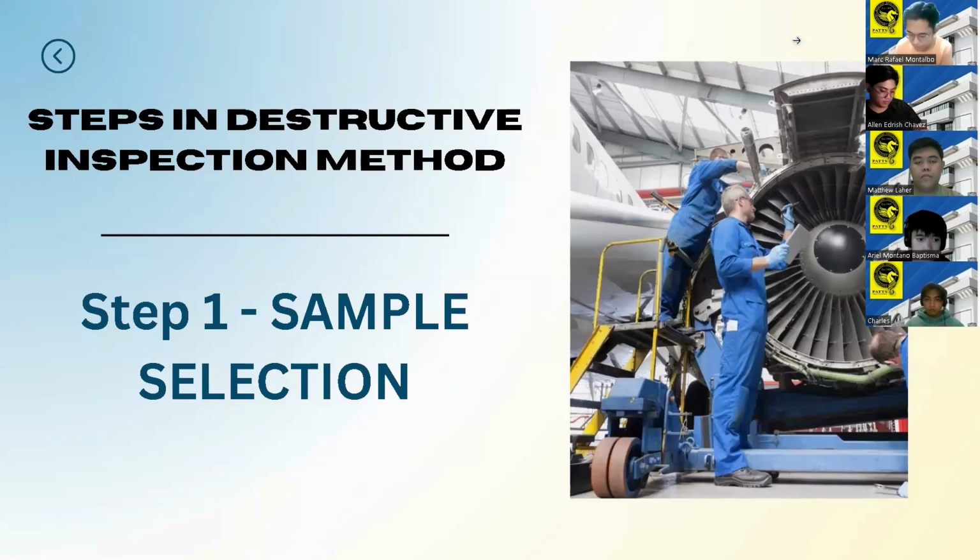So the first step in destructive inspection method is sample selection. In sample selection, we identify and select the test specimens that represent the material or component you want to evaluate. Ensure that the specimens are prepared in a way that they are representative of the actual material or component.